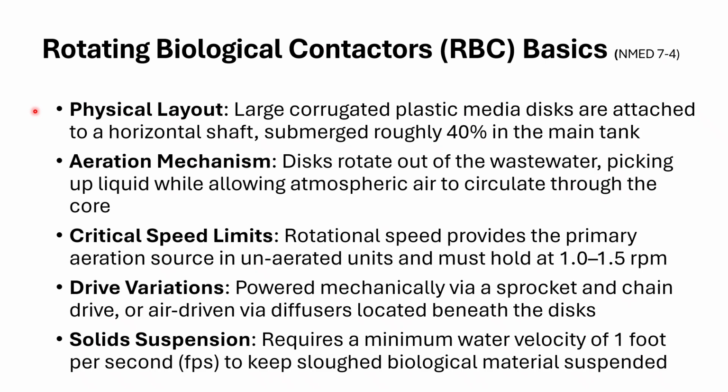So we talked about trickling filters, again, a fascinating fixed media system. The second fixed media system you're going to see on your exams, and you should know something about, is rotating biological contactors, or RBCs. Now let's talk about some of the basics, okay? These are some big drums, if you will, and inside those drums they've got these plastic discs, called corrugated, which means they've got kind of sharp surfaces, as we'll see a little bit.